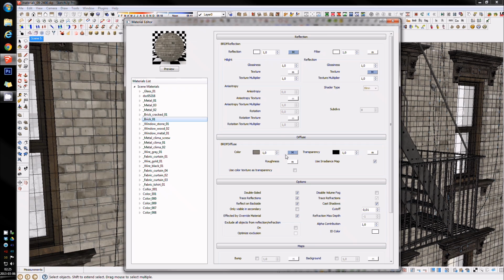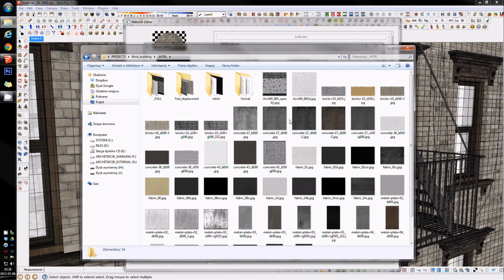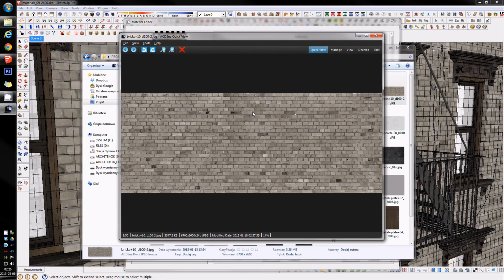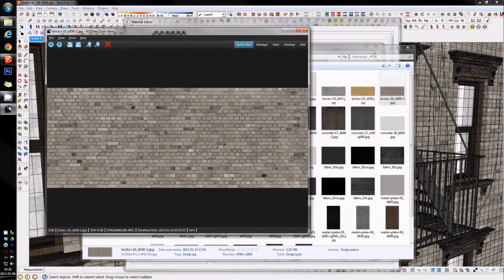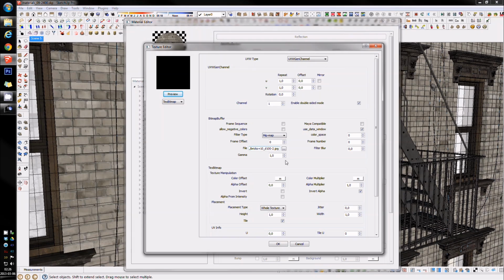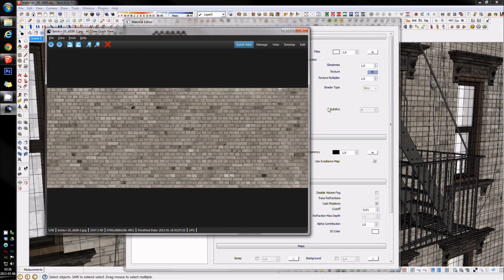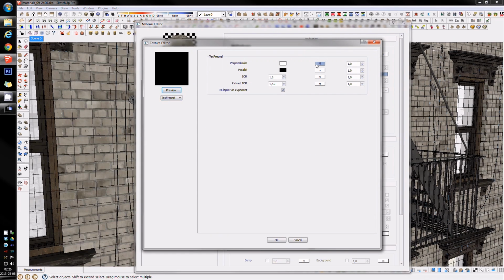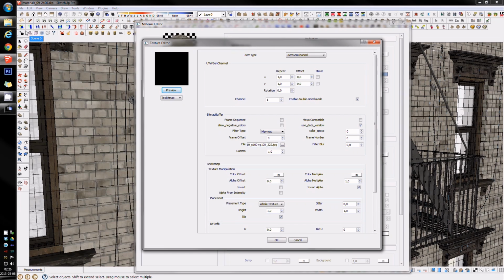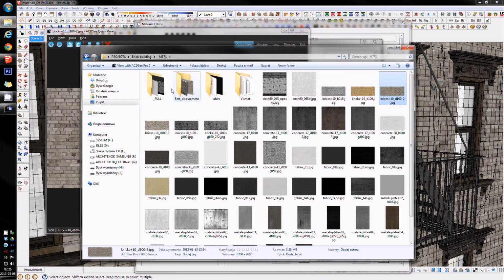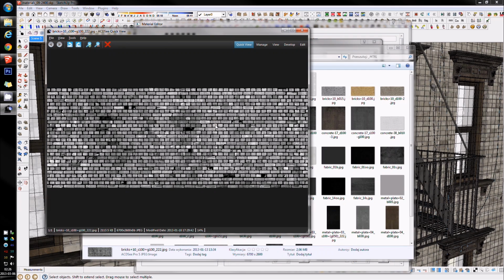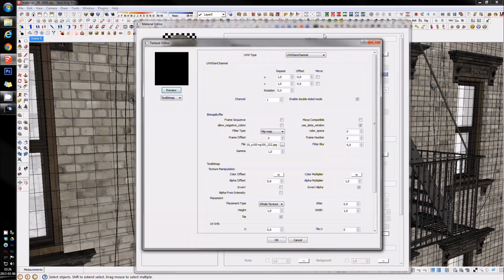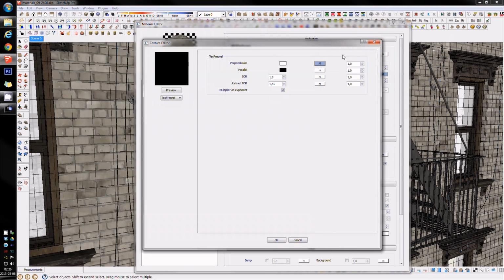The diffuse texture map is simply previously adjusted in Photoshop, some color corrections, stuff like that. Nothing more, no changes at all. The reflection map is of course Fresnel. And map in the next texture, which is the same but the grayscale version, also adjusted previously in Photoshop, IOR 1.8.